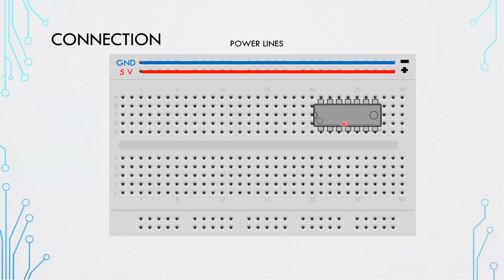Once you place it, don't place it like here. This is the wrong way of connecting the IC, because as you can see, we know that each column here represents 1 node. Once you do that, you connect this leg of the IC to this leg, and this is prohibited in circuits in general. So as we learned at the beginning, if you try to connect any kind of element, don't connect both ends